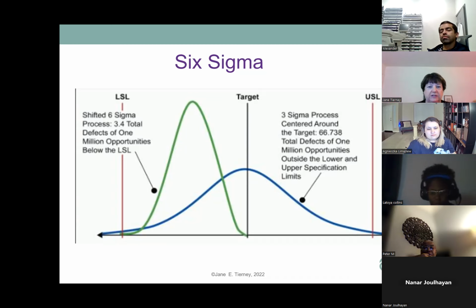Occasionally you'll see specifications that say plus 0 minus this, or plus 0.25 minus 0. That says it's got to be at least the dimension that you're looking for. Can't be less than that if the minus is 0, but it can be a little bit bigger than that. So then what we do typically in manufacturing is we say, okay, we're going to move our target a little bit so that we have more of this bell curve that we can get. So the designers do that for different reasons, but we're usually trying to shoot for being in the middle, right around a desired target. So here's our target.